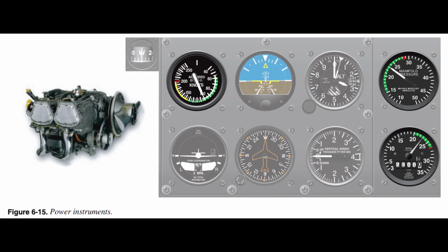As illustrated in Figure 6.15, power indicator instruments include: 1. Airspeed indicator, 2. Engine instruments. Airspeed indicator. The airspeed indicator provides an indication of power best observed initially in level flight where the aircraft is in balance and trim. If in level flight the airspeed is increasing, it can generally be assumed that the power has increased, necessitating the need to adjust power or retrim the aircraft.